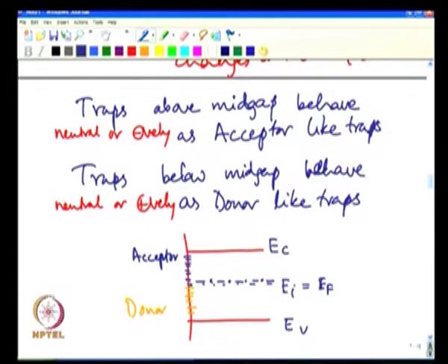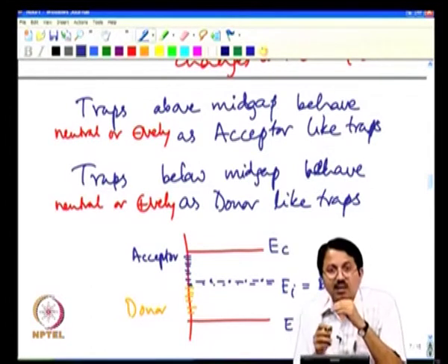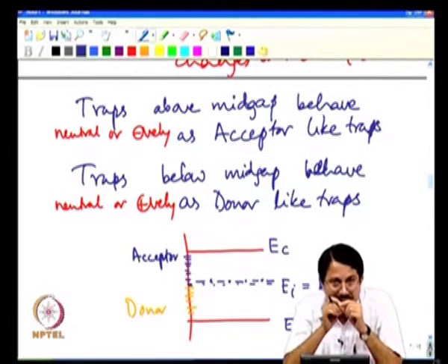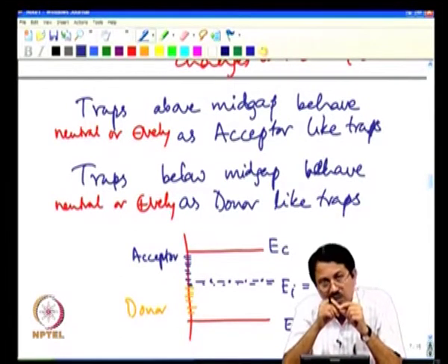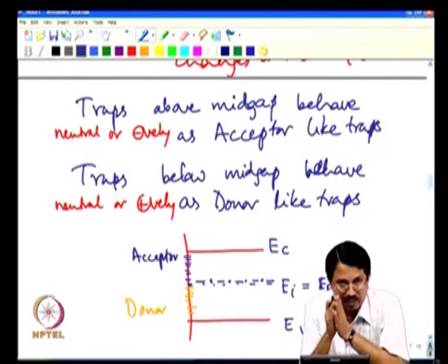Okay. And all these acceptor-like impurities are empty of electrons, they are not filled with electrons. If acceptor-like states are empty of electrons, again they are neutral. In other words, when you have the mid gap condition, when the surface potential in silicon corresponds to the mid gap condition, then interface traps do not give any extra charge. So, that one point which will act as a pivot point will be exactly the same with QIT equal to 0, meaning DIT is equal to 0 or DIT non-zero, that will be the same point.